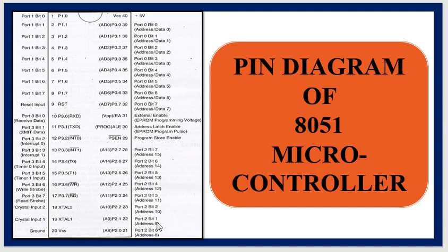If there is no intention to use the external memory, then these port pins are configured as general pins. In case external memory is used, or the higher address bits are used, at that point A8 to A15 will appear on this port.